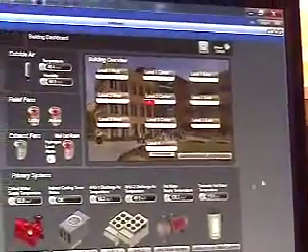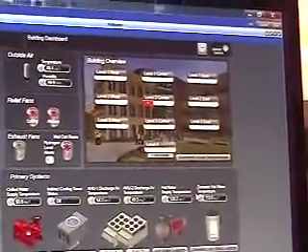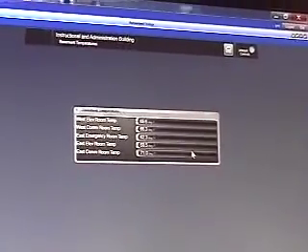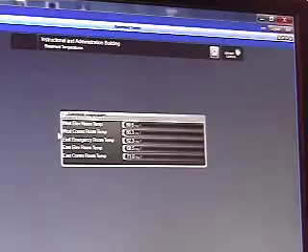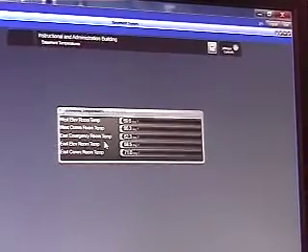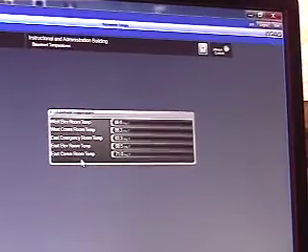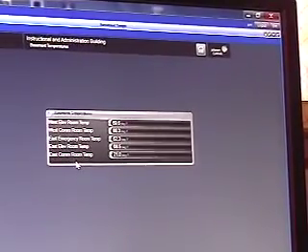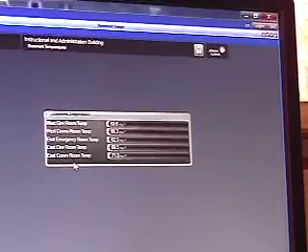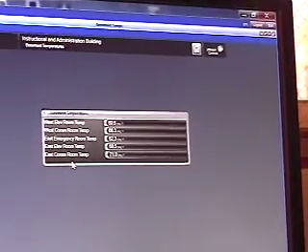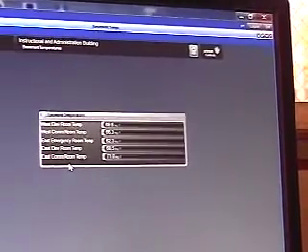From here, we also got a couple other things. We do have some basement room temperatures here. We didn't do a graphic. I don't think you were part of the original walkthrough, but we do have some critical rooms, especially in some of these basements. So we have the west elevator room, west comm room, east emergency room. These right here are temperatures of those rooms. Those rooms are primary cooling. They have fan coils in them. They're fed off house air. As they need additional cooling, they do have standalone fan coils to come on to maintain that temperature.